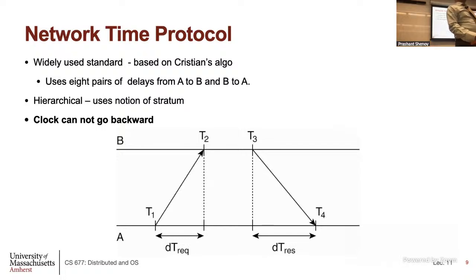Okay. So the quartz crystal says every time the crystal vibrates n times, you say it's 1 second, you tick by 1, right? So you might say, rather than every time it vibrates 100 times, I tick by 1, you might say, every time it vibrates 200 times, I tick by 1. So I've actually slowed it down because I'm not advancing my software clock based on what the actual clock is telling. Right? So that's how you can slow it down. You're not adding a delay. You're just slowing the rate at which your clock is advancing on your machine. And then you wait for the actual clock to catch up to real time.